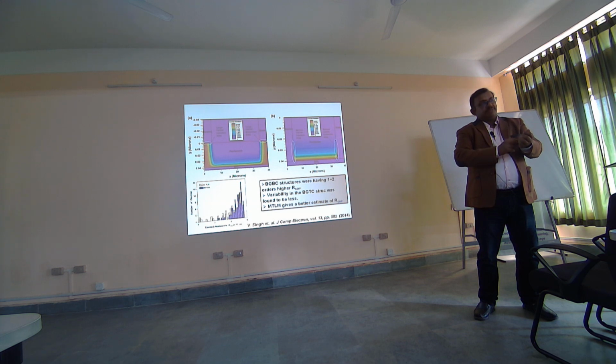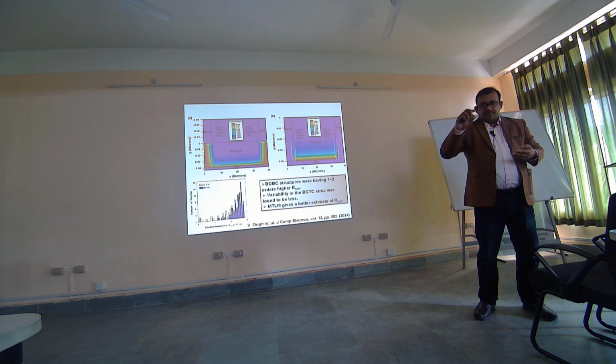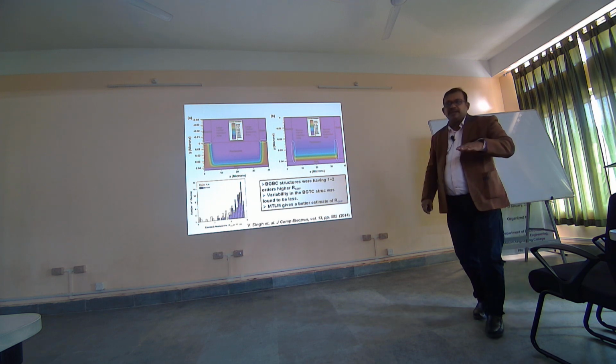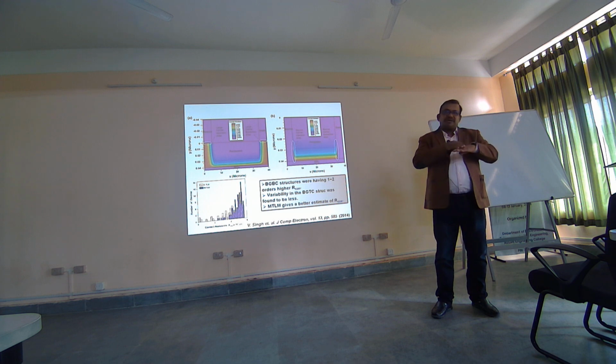One or two essential aspects that you should bear in mind: one is the surface energy of the surface on which you are trying to develop these films, which should be well managed. Sol-gel is essentially a solution-based technique, and most probably you are looking into aqueous media, right? It must be in aqueous media. So in that case, your surface should be hydrophilic. Your surface energies should match.